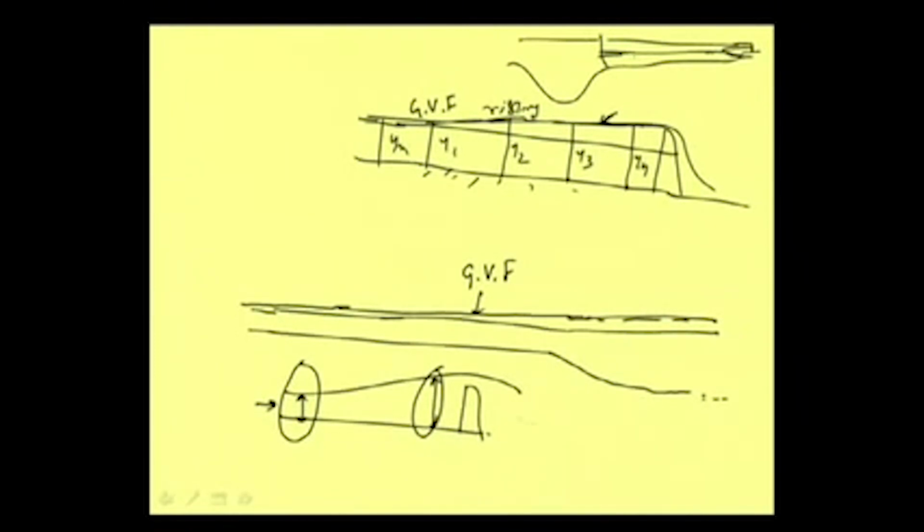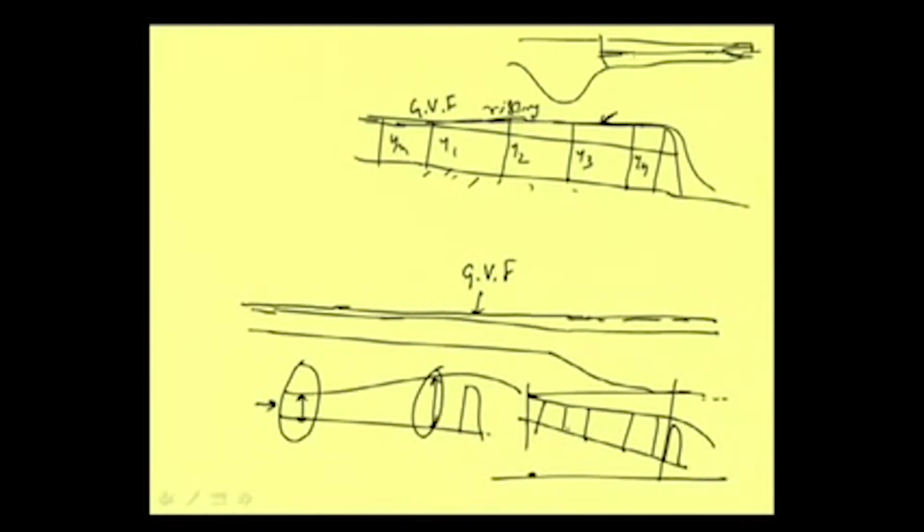And in reality, there will be some slope, like this barrier is there, and then suppose depth of flow is there, and it is rising like this. But if I draw a horizontal line here, or the energy line also if I draw, then you will find that energy at this level is higher than the energy at this level. So, though the depth is increasing, if I draw from a particular datum here, then this is z, then this is y, then again due to velocity we will get v squared by 2g. Here it will be z2, say this is slope z1, y1, then v1 squared by 2g, it is z2, then y2 plus v2 squared by 2g, suppose this much, then we will find that the energy line will be like that, energy slope.